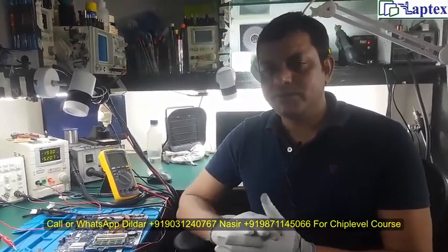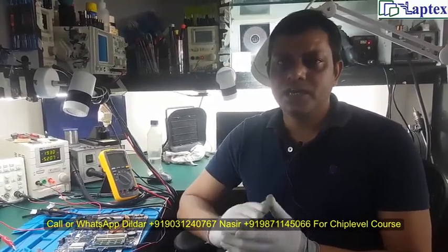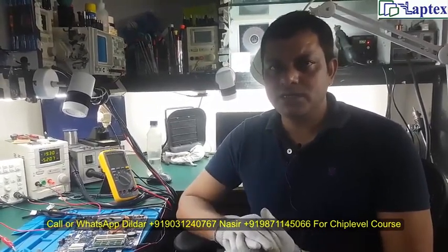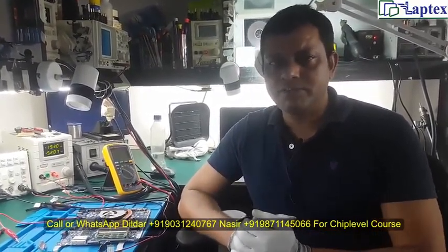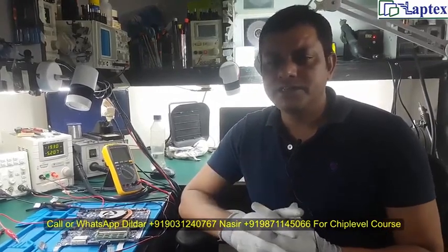PWM checking with the DSO, SDA, SCL, SM bus checking with the DSO, and the RTC section with the DSO. If you haven't seen them as of now, go back and watch those videos first, because this is the last signal which we need to check on the motherboard, the reset signal. The advantage of checking this signal with the DSO is that you cannot identify this signal with the help of a multimeter.